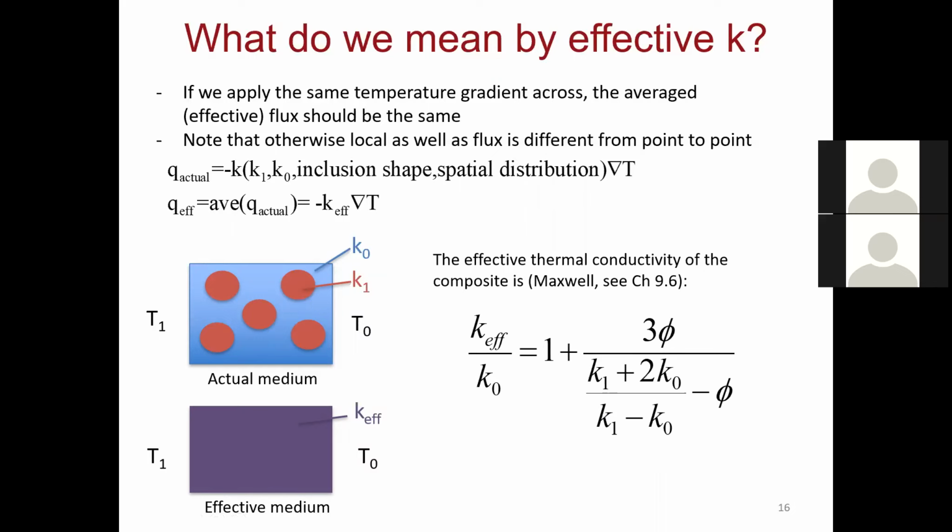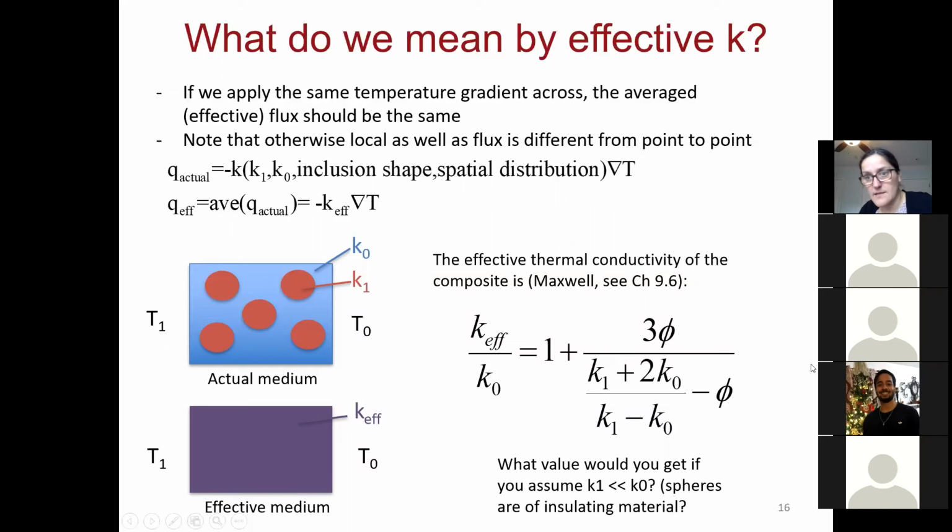However, we also have to understand that there will be a major shift in the value of K effective if these spherical inclusions actually touch. And in all of the applications that we care about, they do. So we will have a compacted granular medium, a close packing of spheres, and those spheres touch at multiple points.